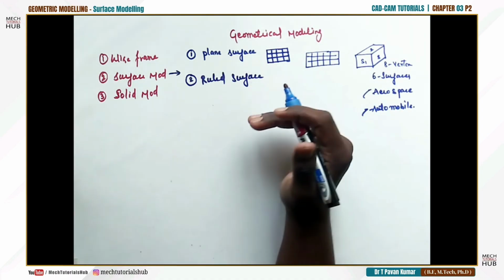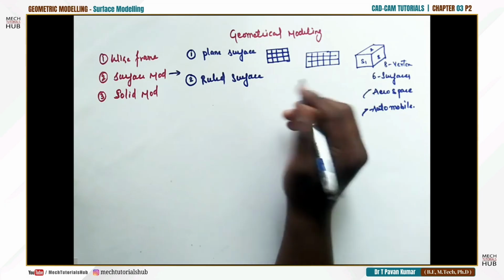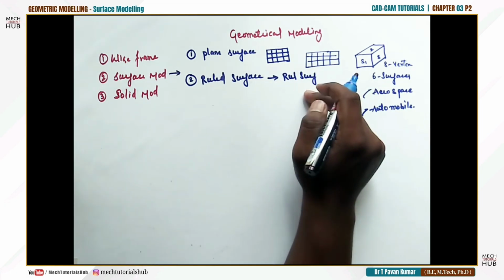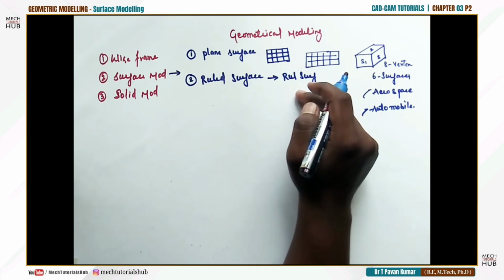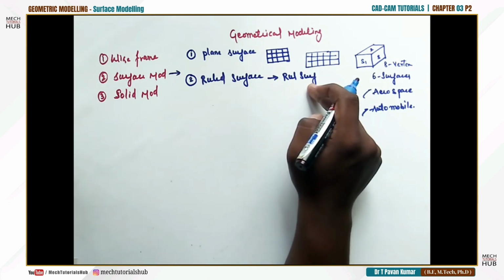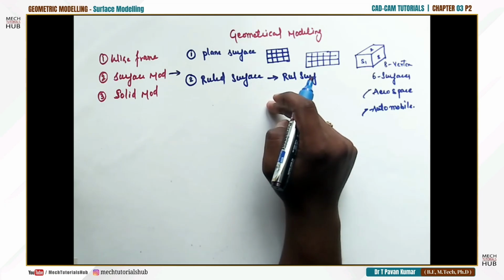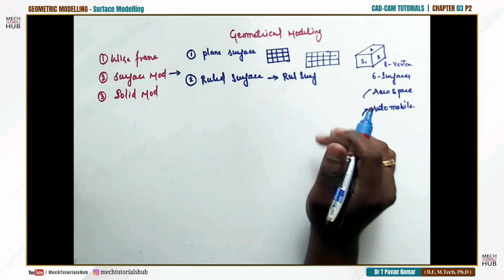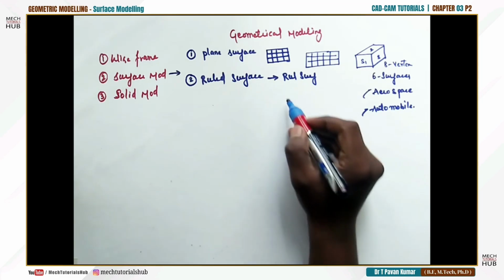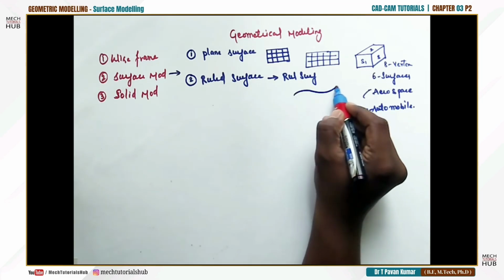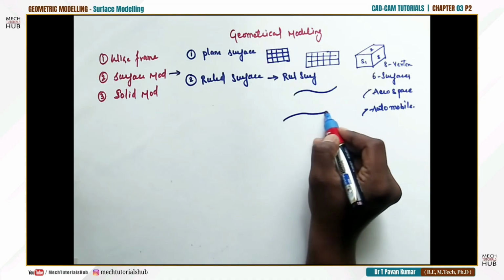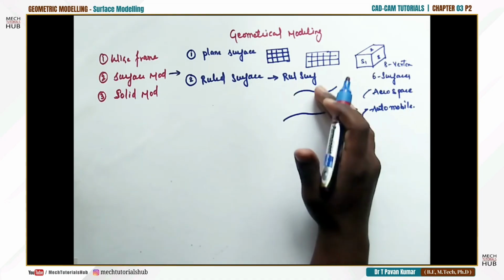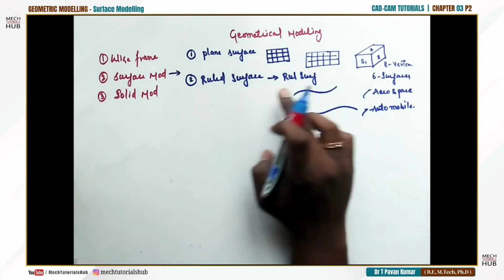You can draw all these in software called AutoCAD. In AutoCAD, the ruled surface command is RULESURF, which can be given in the command prompt. It will ask for options, the starting and ending curves. For this, on the AutoCAD graphic window, I need to draw two curves of this kind, or any other two curves, maintaining some offset distance between them.